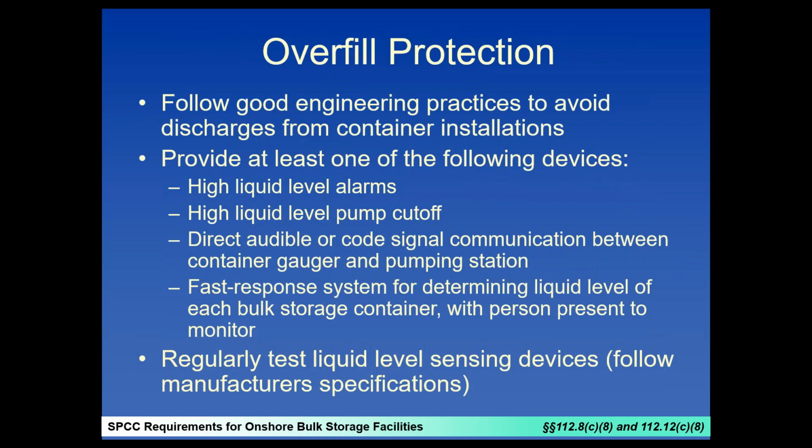This is something I can't preach enough about, and that is oil overfill protection. I was just talking to somebody on the phone right before this, a tribal partner actually, and overfill is super important. You've got to know how much a tank can hold relative to when you're transferring into it, and there are devices that will help you gauge the tank as well as shut down transfer or give you an alarm when the tank gets to a certain level.